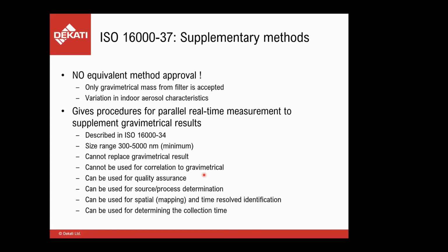When we talk about the supplementary measurement methods, one important thing which is very different to the ambient side is that there is no equivalent method approval allowed for the indoor air measurements. So there is only the reference method and no equivalent methods. The reason for this is that in indoor aerosol characteristics, there is much more variation compared to ambient measurements.